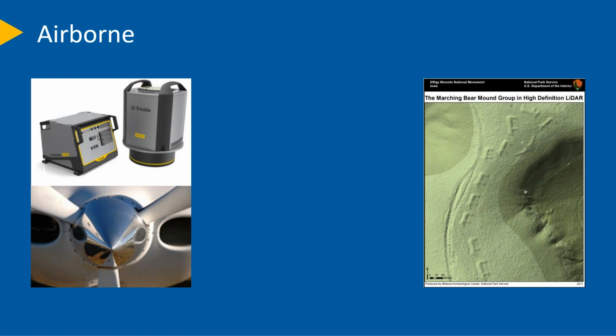Benefits you'll see from airborne LiDARs: you can capture a large area very quickly, with strong lasers and multiple pulses. So it's good for shooting through the vegetation to get the true contours of the ground. I read about these in the news quite a bit, that they'll find new civilizations using airborne LiDAR because it's able to scan through the vegetation fairly effectively and pick up these nuances on the ground to identify where buildings are. So benefits: cover large areas, can provide you a clear view of the terrain.